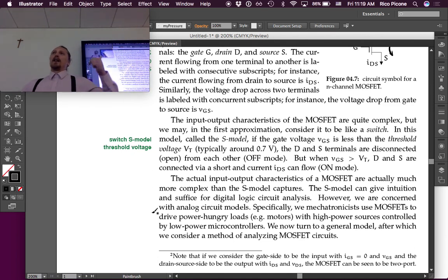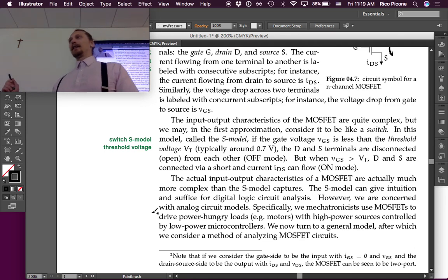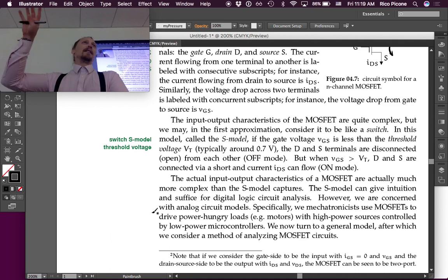Especially if you're just going to turn something like a fan on and off, this is definitely the way to go. In the example today we'll do a circuit where you can drive a load with a MOSFET. Just pop it in there, and then you can control a bigger supply. So it's super useful, the MOSFET.